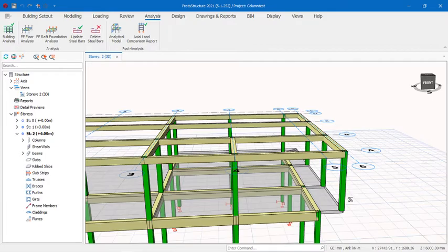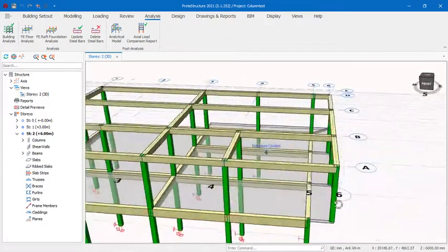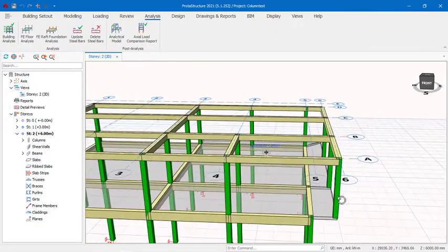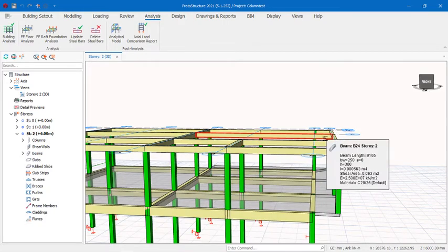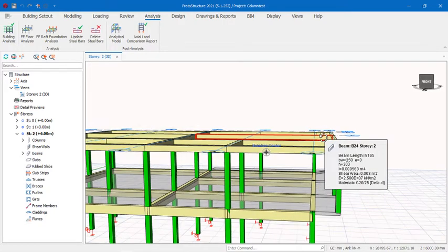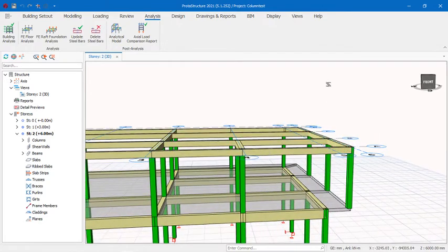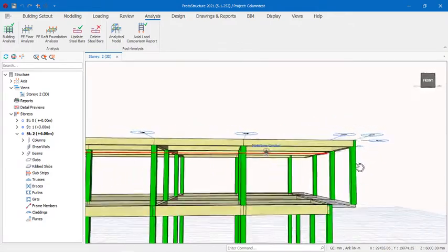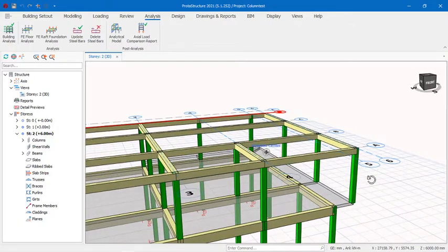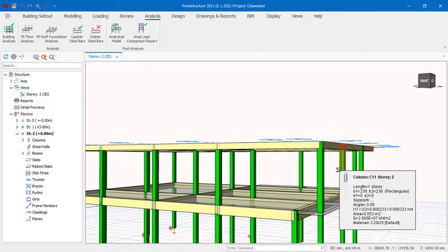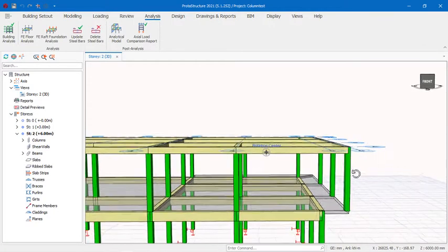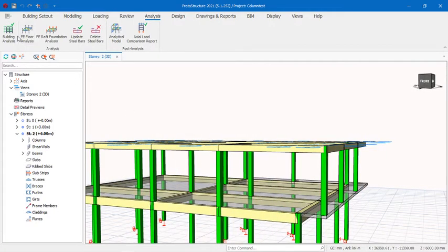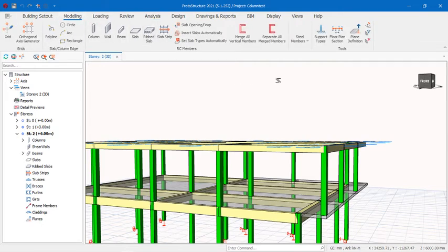But let me save you all that stress and show you what you can actually do, which will also be helpful if you have more than two or three suspended floors, so that the load can accurately transfer from one column in the upper floor to the other columns. That is how you can get the best from the software, so that it can accurately do a load chase down from the subsequent floors. So I will show you what you need to do. Come to the model now.